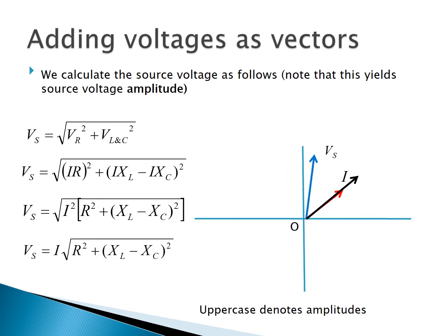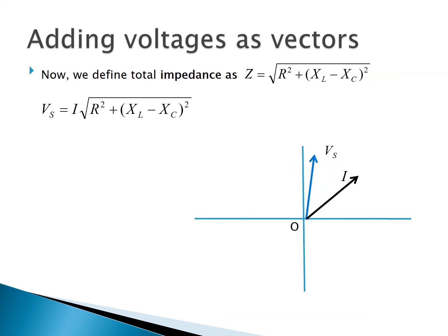And further separating this equation, we have some equation that looks like V is equal to I times R again, sort of like an Ohm's law type equation. And so now we're going to find something called total impedance, which is Z. Okay, so total circuit impedance is equal to the square root of resistance squared plus XL minus XC squared. And then that allows us to write the V is equal to IR relationship that we're looking for here.